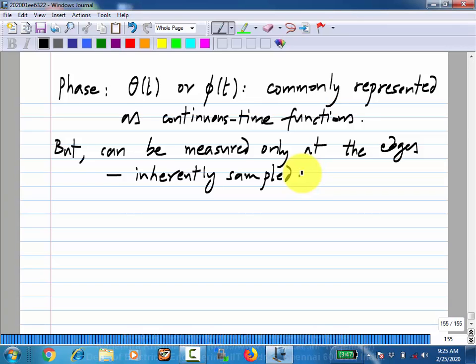Like when you found out the phase noise of a divider, for instance, right? The jitter is a discrete time function, and what is this divider doing? It is dropping samples of that discrete time function, right? It is taking one out of so many samples. To compute the spectral density, you had to use that description. You assume that the output jitter has the same variance as the input jitter, but it will have only one out of every m samples, and then found the spectral density and so on.